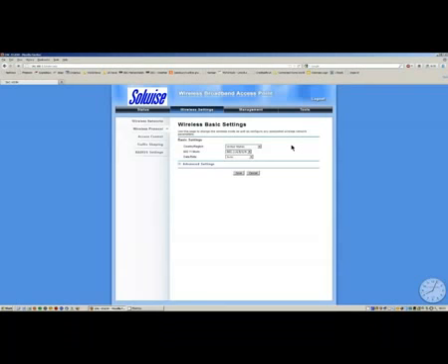Anyway, that's what they've done. Now, the device by default has a 10 dB internal antenna. So if you actually set this to United Kingdom, you'll find the power drops right down to about 10 or 11 dBm as the output power maximum, which, alright, is okay if you just want to use the built-in antenna and you're just trying to cover a small area.